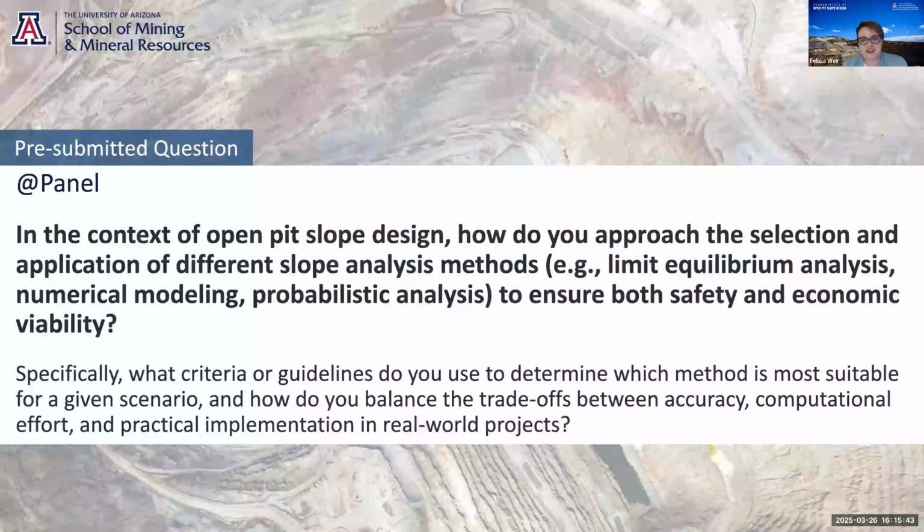I was just going to support what Carl and Joe had said, and essentially a little bit on what Rob said too, in terms of it depends on the scale of the project and the life of the mine that's being proposed as well. If you're dealing with a 60-meter deep, short, 1 or 2 year project versus a kilometer deep pit with interaction with existing underground, things like that, they're all very different. And so you have to think about what's controlling your slope design and what is the life of the mine and the scale of the project that you're looking at.